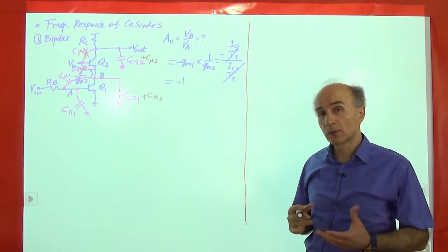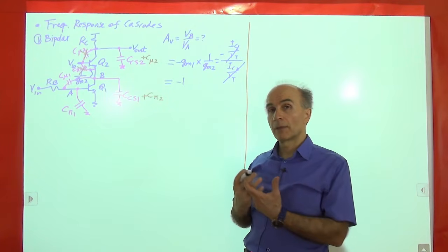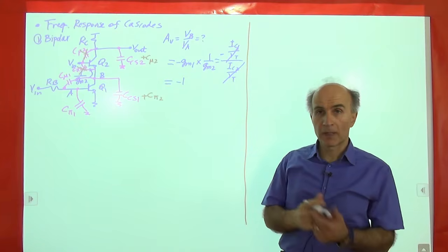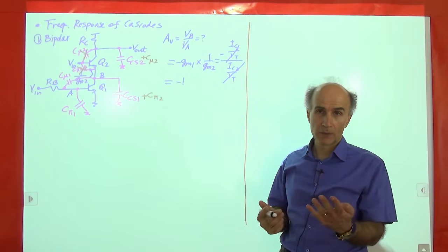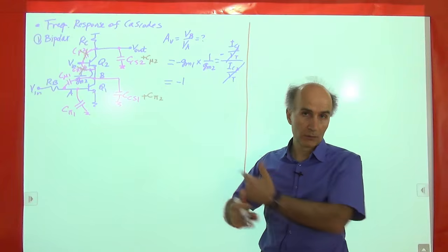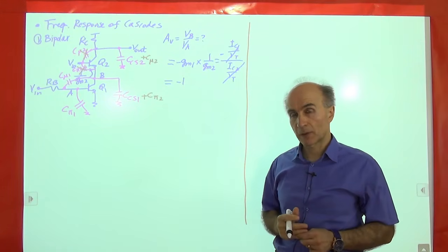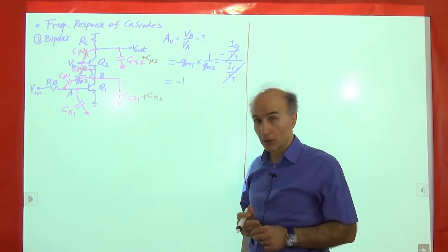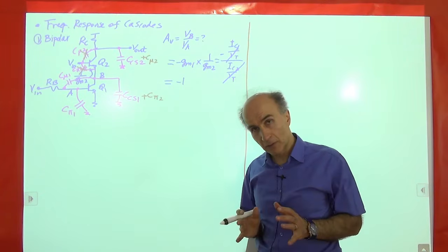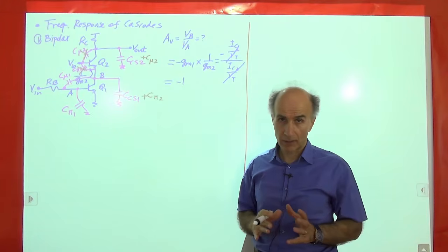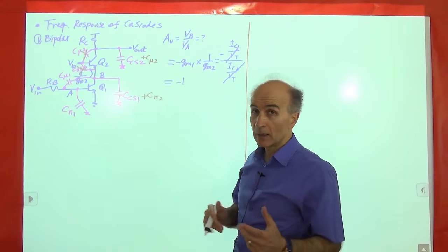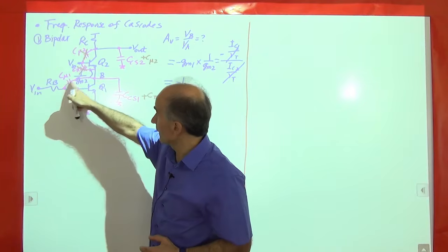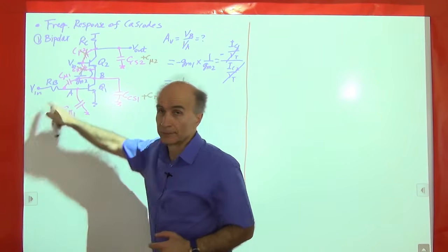Okay, I would like to determine the frequency response by finding the poles by inspection. If I have the poles, then I can use Bode plots to figure out what the frequency response looks like. All right, so then for every node, I need to find the capacitance to AC ground and the resistance to AC ground. The difficulty relates to node A and node B because we have this capacitance going between the two.